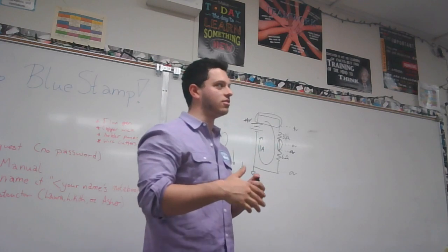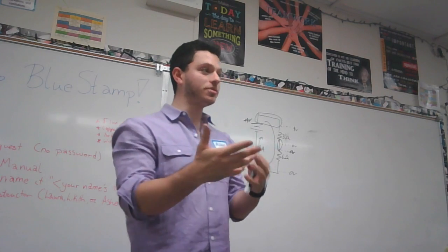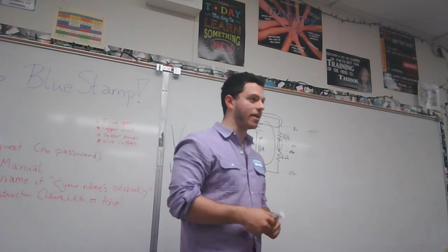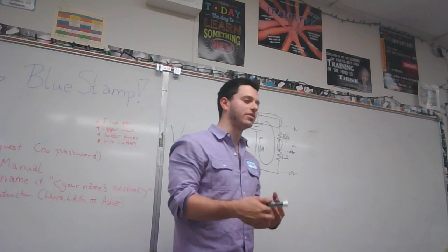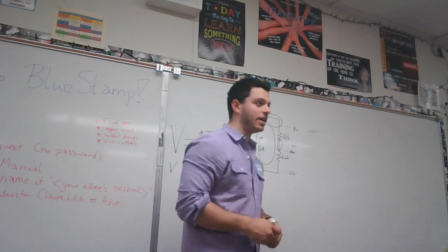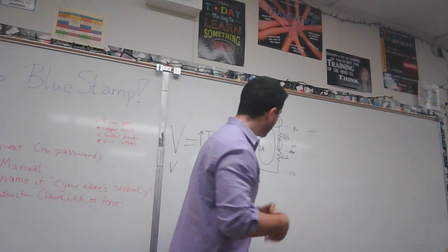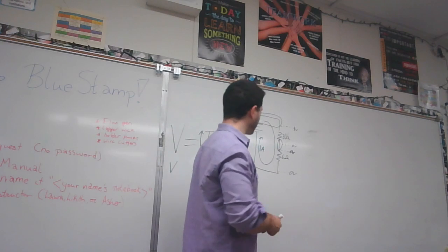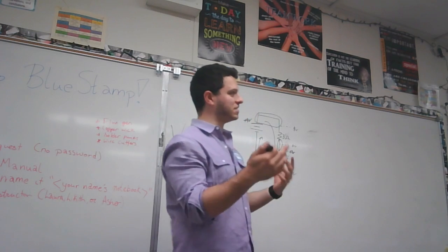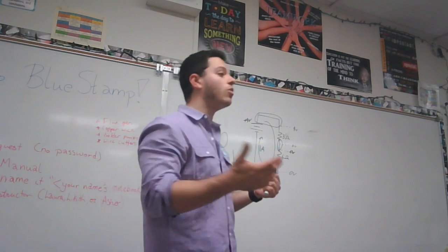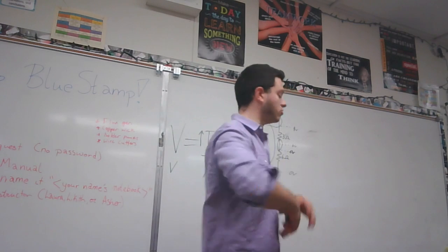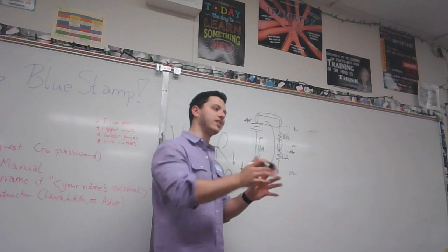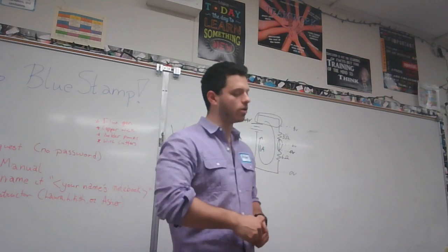In a lot of the things you are doing, with the size of the wires you will have, you can pretty much think about the resistance as negligible, but you are absolutely correct in the sense that wires will have some resistance. In this case, it actually would matter because these are relatively small resistor values, but it might have a resistance of like 2 milliohms or something, whereas doing the full math would just make more sense not to worry about it. But you're not wrong at all. That's absolutely correct.